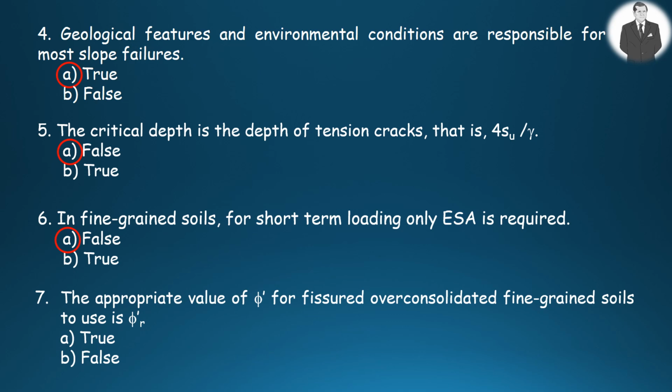Seventh question: the appropriate value of phi prime for fissured over-consolidated fine-grained soils to use is phi prime sub r. True or false? Yes, it is false. Very good.